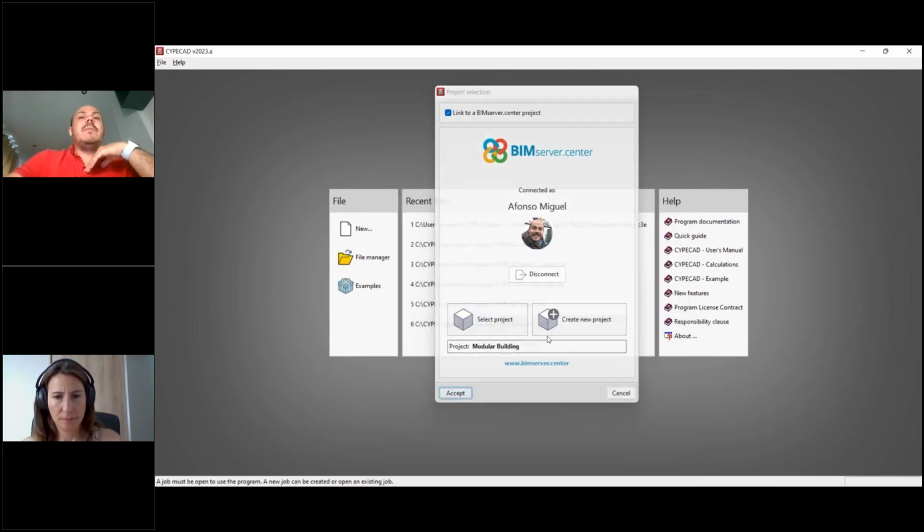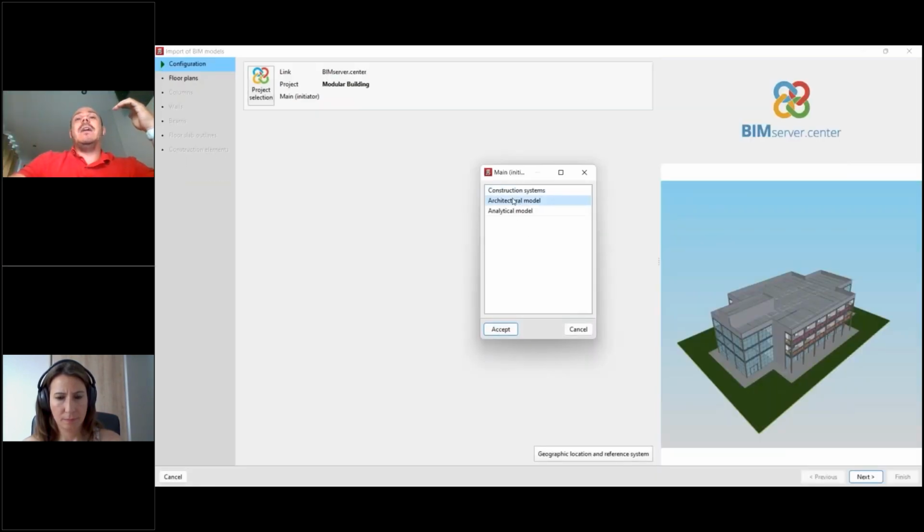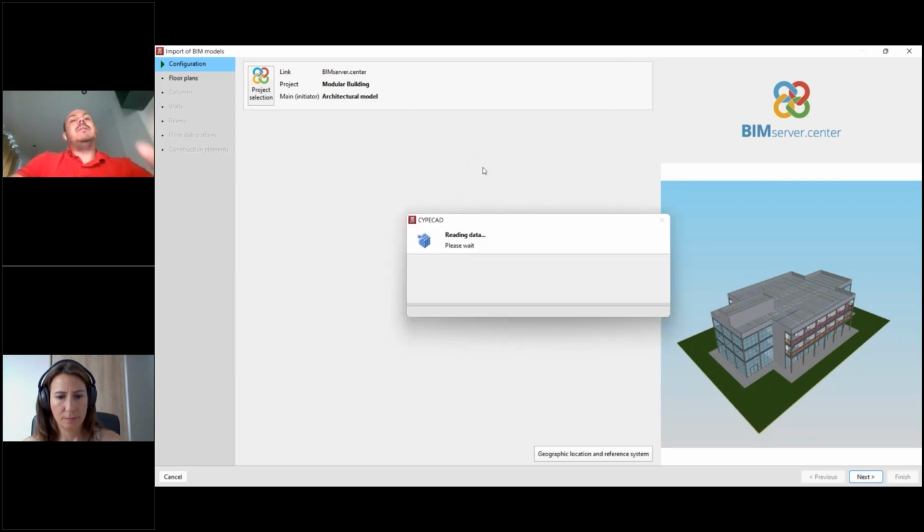I'm now connected. I'll accept, and now I will start importing the information from the architectural model that was exported from CYPE Architecture to BIMserver.center. Okay, so let's accept it, and CYPECAD will start reading the information that we have in our model.